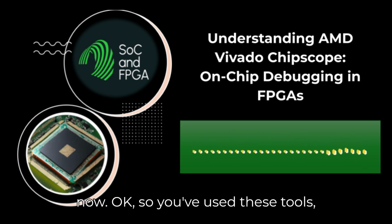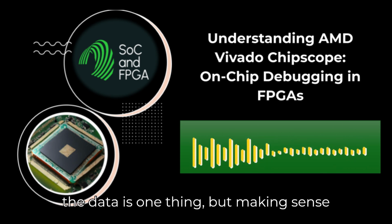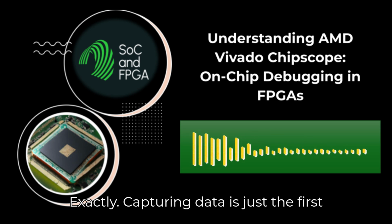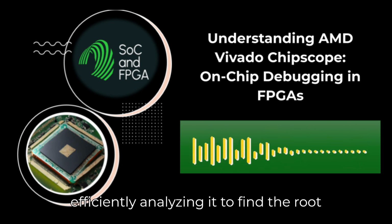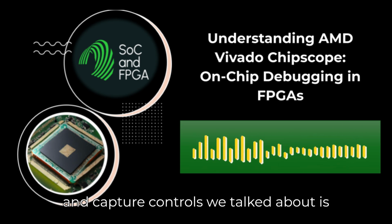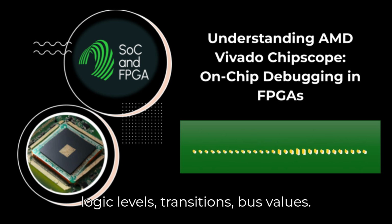Okay, so you've used these tools, you've automated the process, you've captured the data, and now what? Getting the data is one thing, but making sense of it is the real challenge, right? Exactly. Capturing data is just the first step. The true challenge lies in capturing the right data and then efficiently analyzing it to find the root cause. First off, mastering those trigger and capture controls we talked about is essential. Basic triggering is simple logic levels, transitions, bus values.